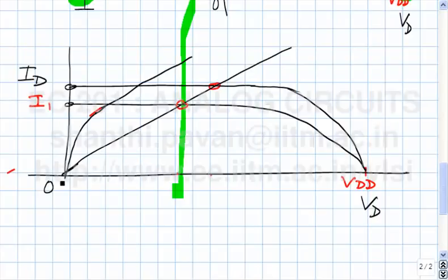So we are saying that if we had a linear resistor for the load, then to get a very large gain, we need to have a larger and larger supply voltage. Now the next thing is, can we do something about this? Because having a large supply voltage is kind of a pain, fundamentally because it costs a lot of power. Alright, so is there any way of getting large incremental gain without having a large power supply?